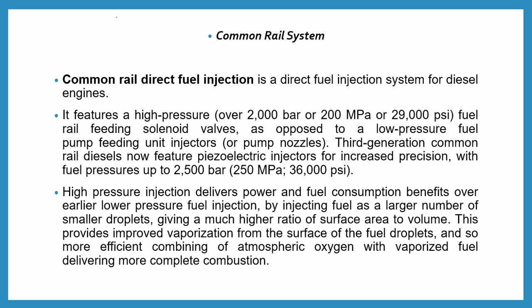The third generation common rail diesel has a new feature known as the piezoelectric injector. For this reason we increase the fuel pressure from 200 megapascal to 250 megapascal.